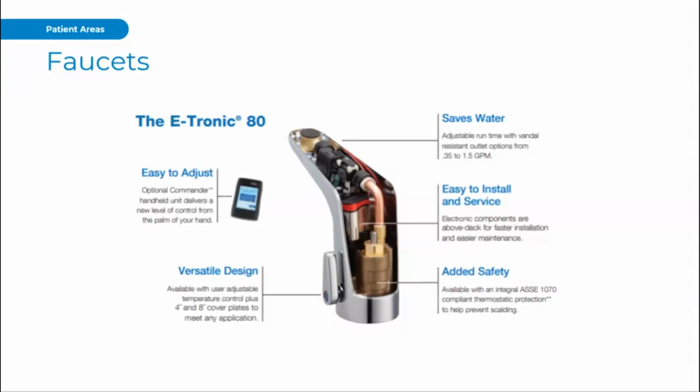We see everything from healthcare grade laminar flow at the base of the spout, goosenecks that avoid the drain, to maybe call it an IPAC intent, where it's a laminar outlet, and this faucet actually has a laminar outlet available at 0.5 GPM, so you can get low flow as well as provide that infection control.